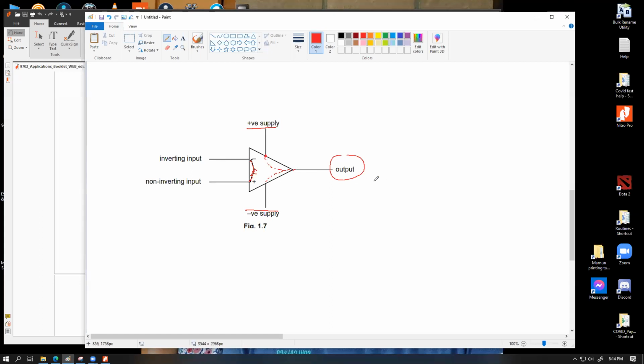What I'm trying to say over here, try to understand. Voltage doesn't walk from one place to another like current. Voltage is actually the push or pressure on charges to flow from one place to another. So if you want to have exactly the same voltage from this place to this place, it means that whatever lies within this op-amp structure to connect this end with the output side, or the negative supply with the output side, these parts do not have any resistance whatsoever.